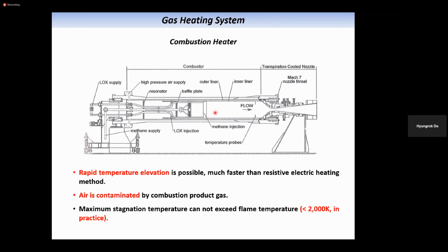You can measure the pressure pretty accurately without an optical measurement method. And then maybe you use the optical measurement for measuring a density at the location, maybe at the center where the temperature is high. Then you will have the density information and the pressure information, and that will help you to extract temperature information. That's how most laser diagnostics works.